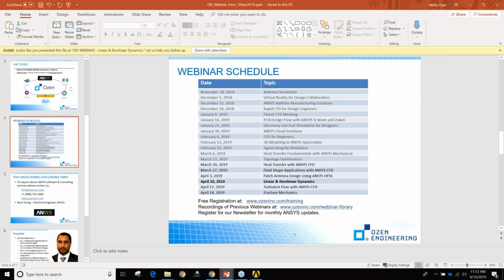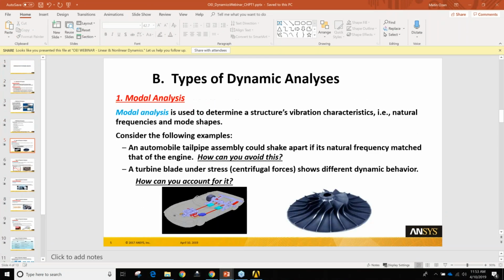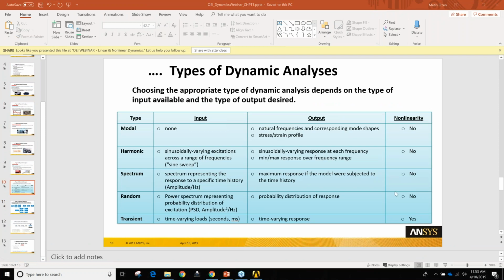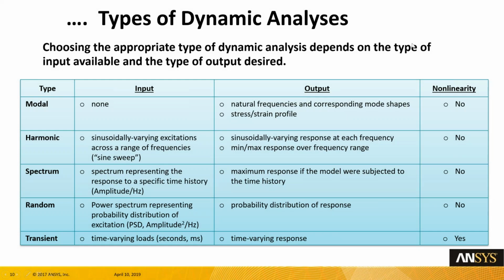If I go back to this chart over here, in response spectrum analysis, there are really no nonlinearities allowed here. So if we want to account for any nonlinearity, we have to do a transient time domain simulation, which means transient structural analysis over here.